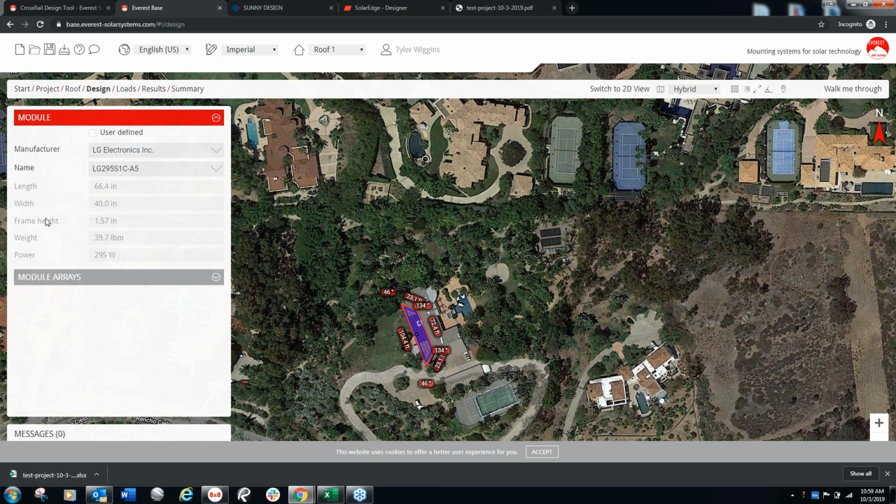The way we could get this quickly to our customers was just choosing some typical rules for clamping locations. For most module manufacturers, the quarter points on the long side and the short side are generally the areas where these modules are clamped. So that's the rule it's assuming. It gives a space on that long side and short side that is about the quarter point to the fifth point. I think it's some very small range in there that we chose based on some select major module manufacturers that we worked with, and kind of have a general rule for it.